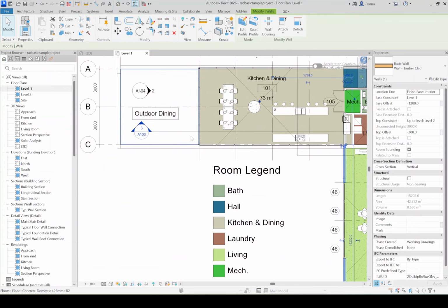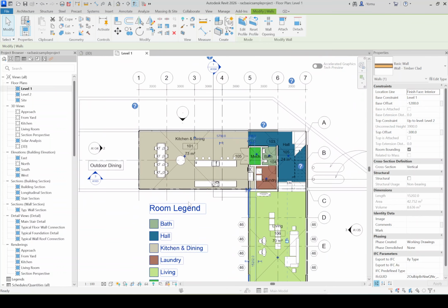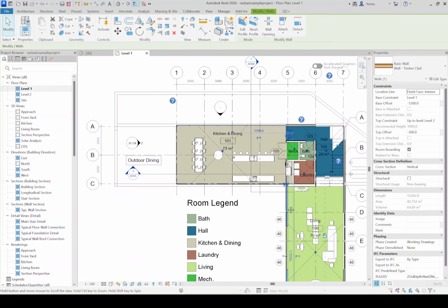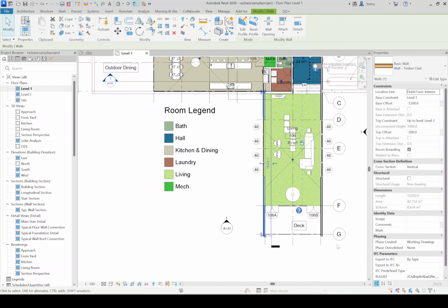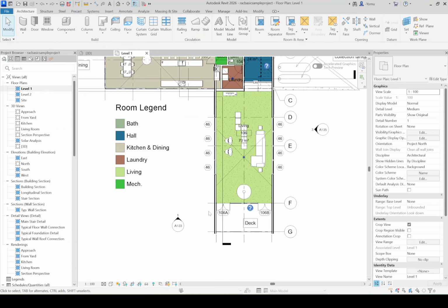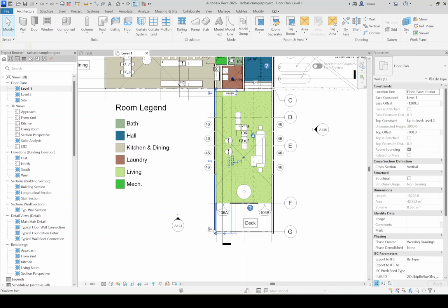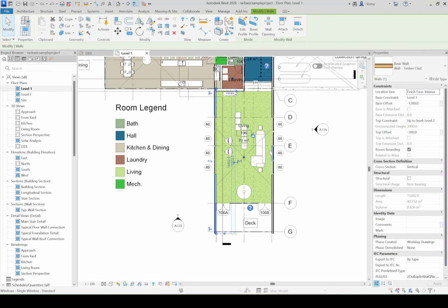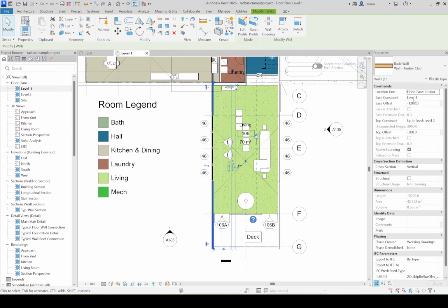So now at this wall, we have from C5, basically, from C5 until G5, and it's also the same here. Let's also check the values of the timberclad wall on this side. So now we have Level 1. Instead of no offset, we have an offset of minus 1 meter, 0.2. Now we have here 300 millimeters. So we have to make sure that we also adapt to these values.